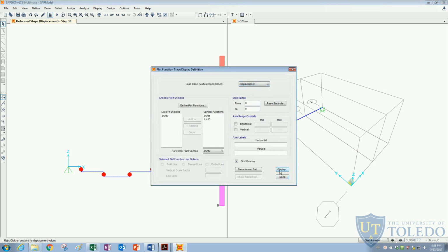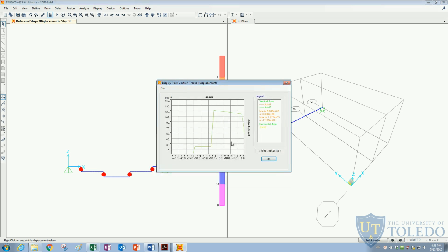I can change that to displacement, and here you can see displacement analysis, force displacement response. And you can also see that it looks a lot like the hinges force displacement diagram that we inputted on our shear hinges. And the reason for that is because since this being failed on shear, the force displacement basically followed the shear capacity until it fails.